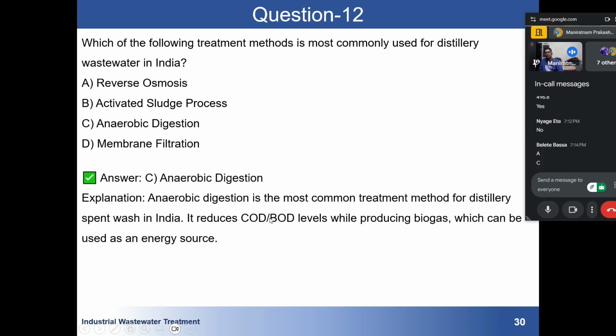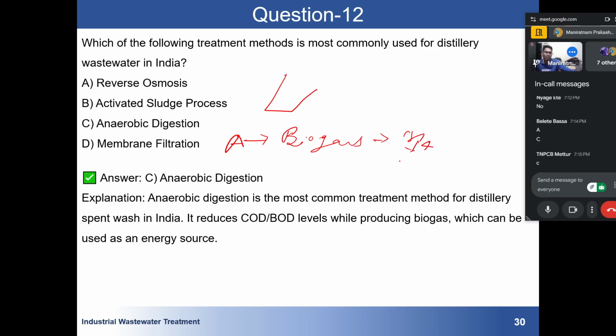That is, we have the anaerobic digester or reactor process, which helps in biogas production also, biofuel in the form of methane, used for burning. So it's a sustainable method also. There are several methods: the anaerobic digester, then UASB, then HAR, that is the hybrid anaerobic reactor.